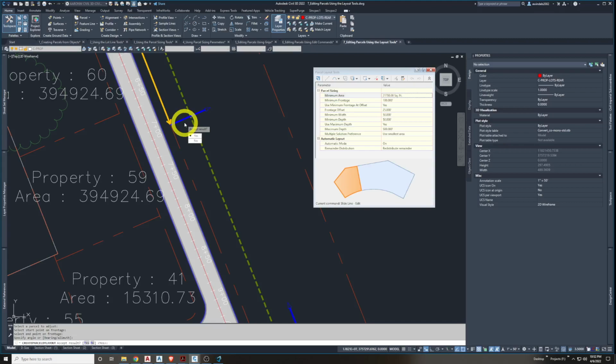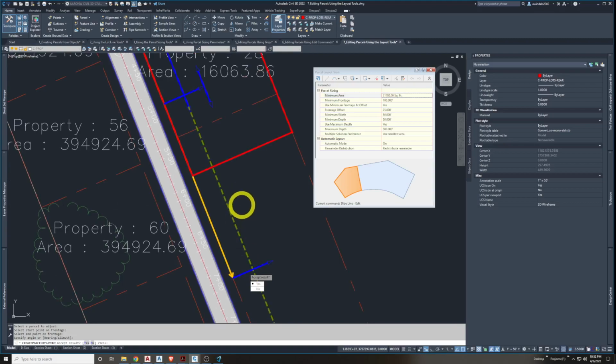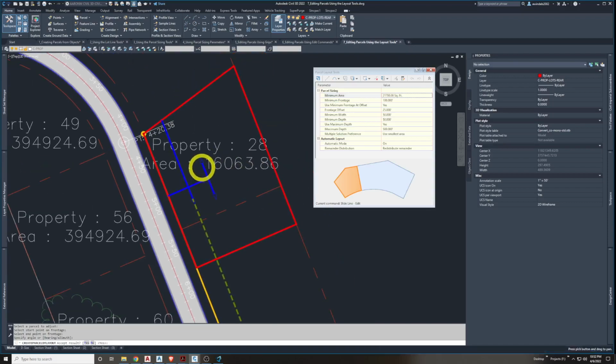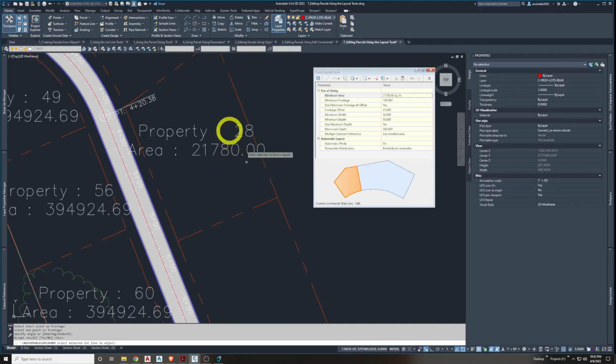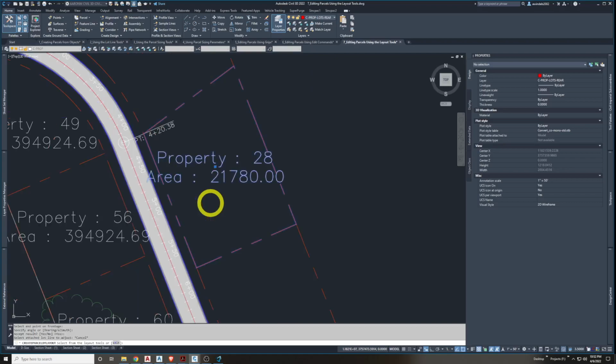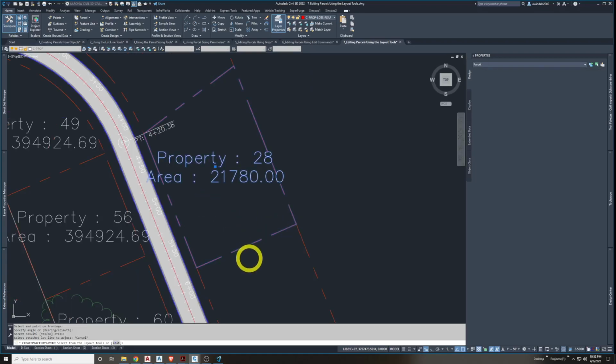I'll zoom up here to accept the resized parcel. Yes, that new dark red. I'll accept that. It changed this parcel to exactly half an acre, 21,780 square feet, using these tools. It did it really surgically without having to calculate it a bunch of times, which I can tell you I've done manually a lot. Let's press escape a few times to exit all these commands.